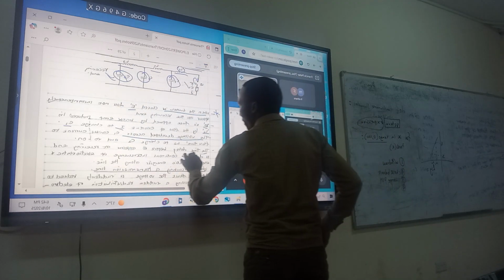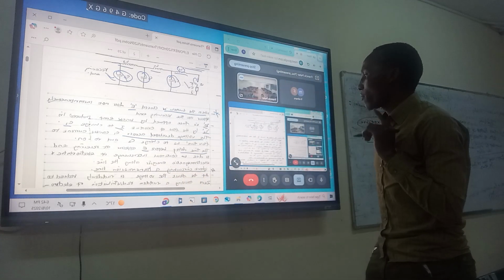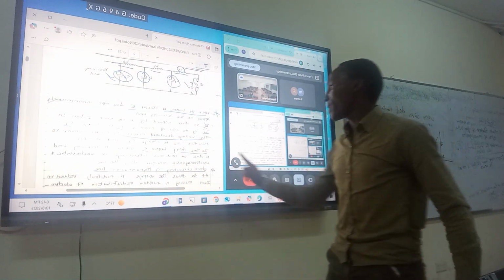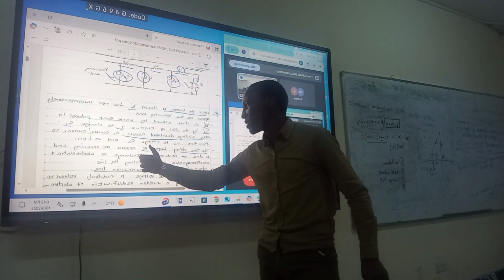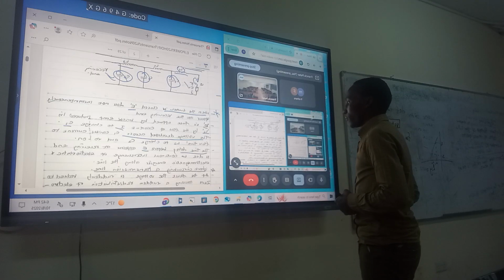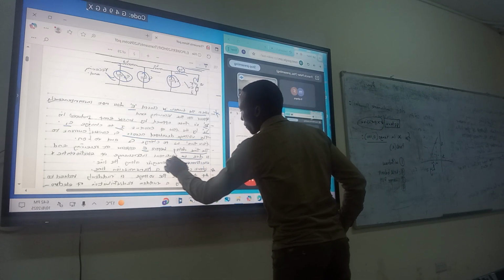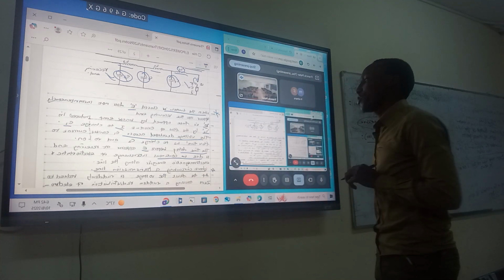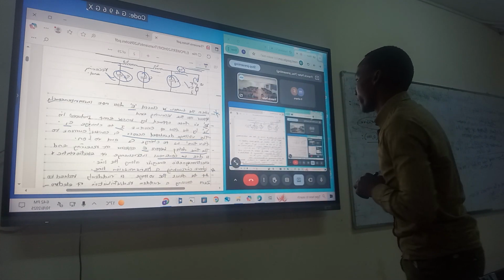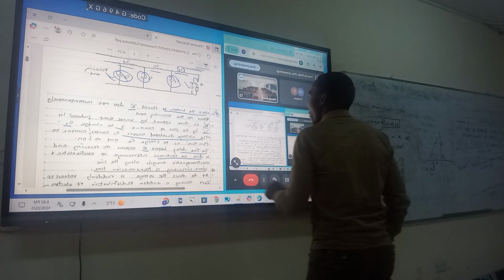Now, there is that time delay before E. Remember, E is our switch. So the time delay before our switch, that is E, appears at the receiving end is due to the continuous interchange of the electrostatic and electromagnetic energies along the line.